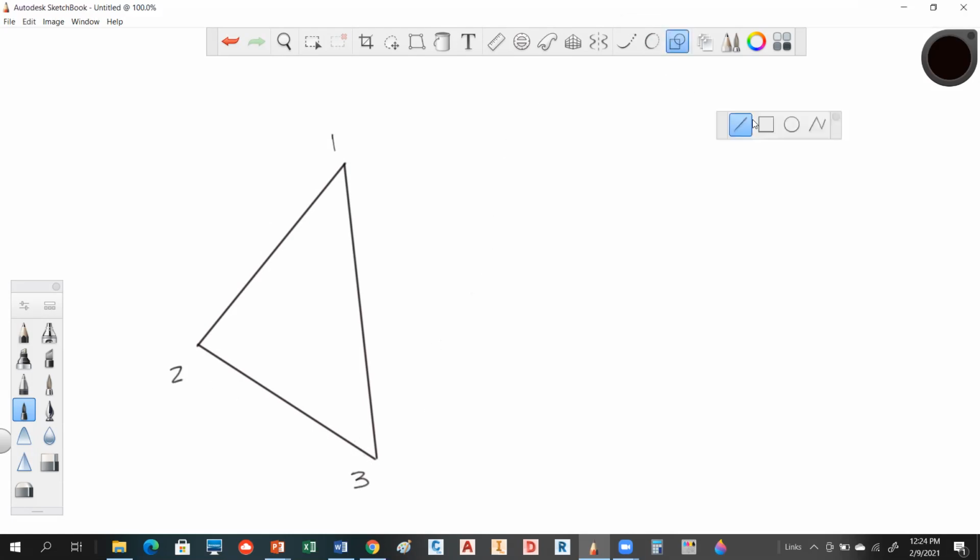So in this process, let's say you have a building out here that's not staked out yet, but you want to stake it out because you need to put the foundation in and all that stuff. So your engineers have calculated the positions of the corners of the building, and they have given you good northing and eastings for each of those points. So we have northing and easting on each one of those. Northing and easting here, northing and easting here, here, and here.